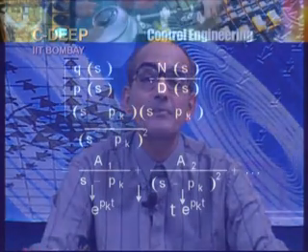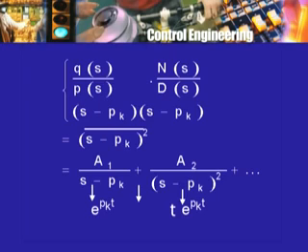What if P(s) itself has a factor of multiplicity greater than 1? P(s) itself has (s - pk)^2. Well, what we have done will convince you that if the pole is a good one, then (s - pk)^2 is no problem. If the pole is a bad one, then the (s - pk)^2 just makes the problem from bad to worse.